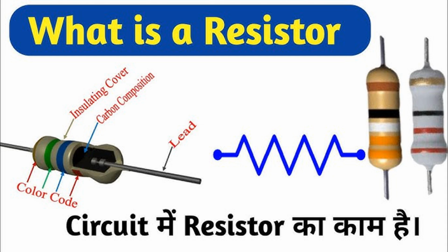How it works: A pull-up resistor is connected between the input pin and the positive supply voltage, VCC. When no active low signal is applied, the resistor pulls the input to a high voltage level, typically the same as the supply voltage. When an active low signal is present, e.g., a switch to ground, the input is pulled to a low, logic 0 state, overriding the effect of the pull-up resistor.